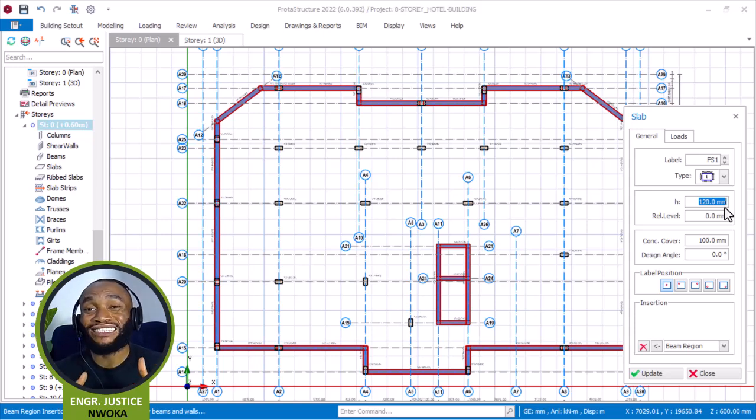But for slab raft design, you cannot assume 200 as the minimum depth. It cannot pass the design, because what is carrying the structure is the slab. Knowing the building is 8 stories, we will start our assumption at 750 depth of slab.